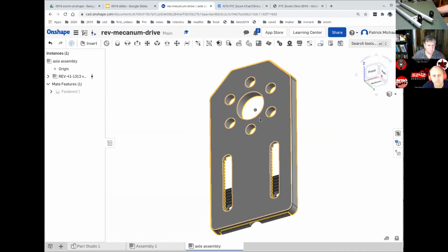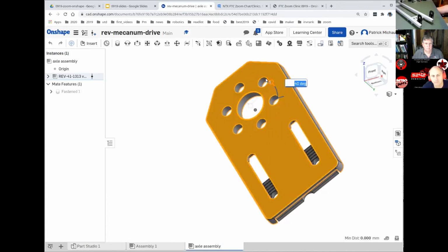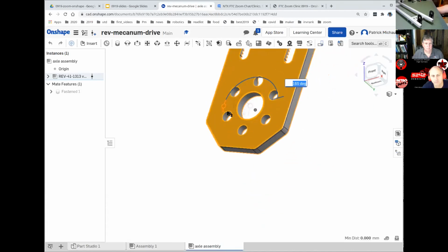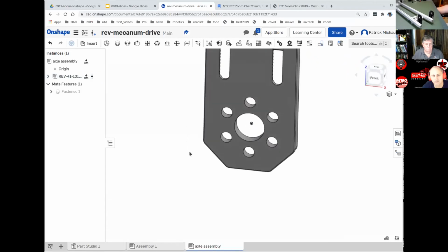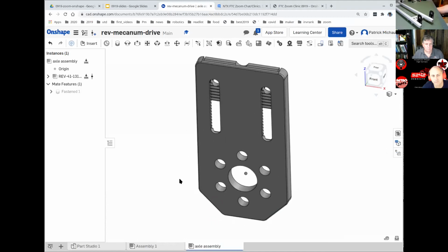Okay, so I'm going to turn this a little bit. So let's turn there. Let's go to the center of this circle here. Let's move this guy to the center of that circle. And I'm going to do a 180-degree turn just so it's upright. And then now I'll fix it in place. That's just going to make it a little bit easier for me to follow what's happening with this model. Okay, so that's one of the indexable motion brackets.